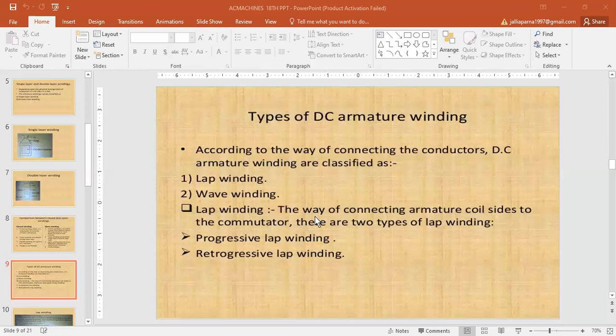As a matter of precaution, it should be kept in mind that all these pitches, normally stated in terms of armature conductors, are also sometimes given in terms of armature slots and armature bars, because the commutator is after all an image of the winding.